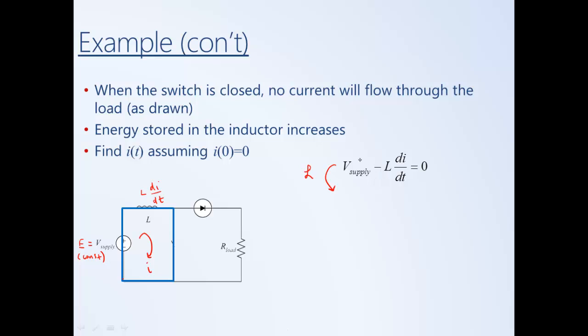The Laplace transform of a constant, in essence, we treat like a unit step. One way to think about it is that initially, let's say the power supply is turned off at time t equals 0, you flip it on, and so it behaves like a step. So the Laplace transform of a constant or a step will just be E over s.